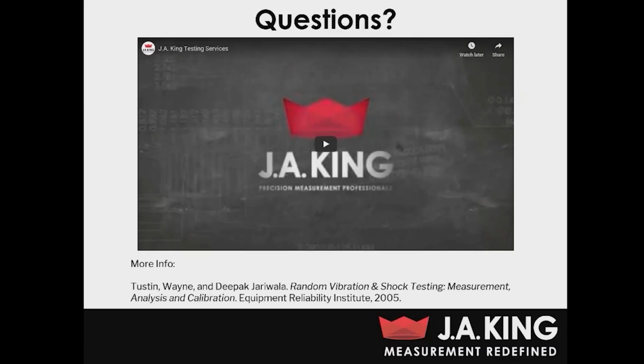So what I like to say is if you know the weight of your DUT and you know the profile, you can always send that information over to us, and we can put that into our controller software. And that way we'll get a green light on whether or not we can go ahead and run your test. And if the fixture and DUT are over what we can perform with that specific profile, we can talk about changing up the fixturing configuration as well to help reduce weight, or we can potentially even take out the head expander and just bolt directly to the armature.